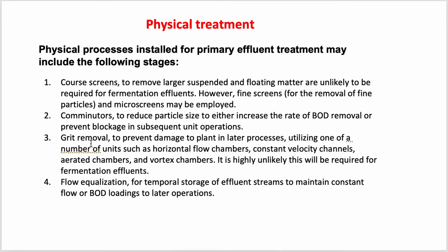Then grit removal. Grit removal is used to remove the sands, grit, etc. and it is necessary to prevent damage to plant in later processes.